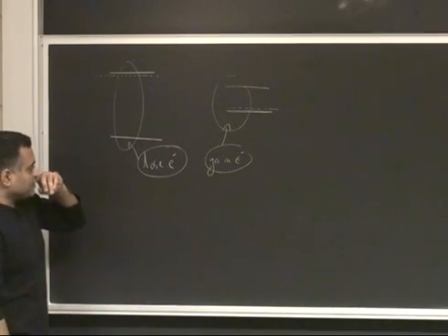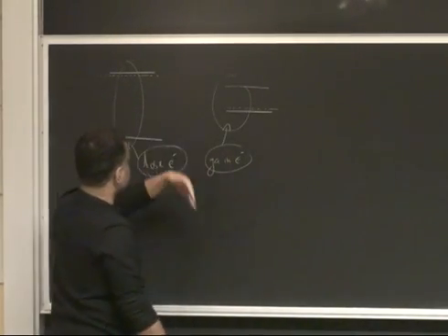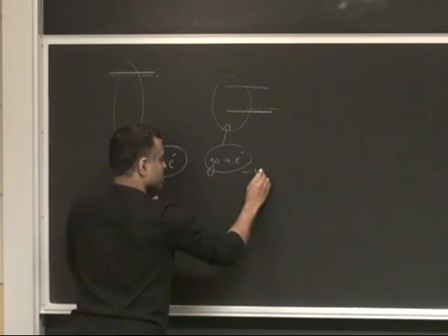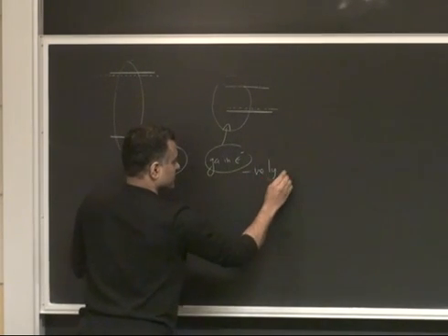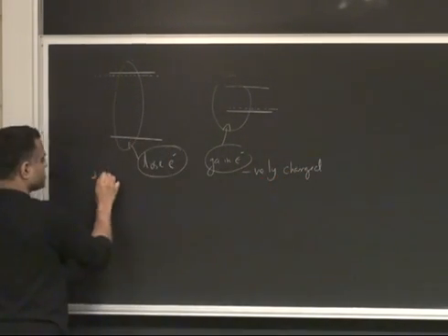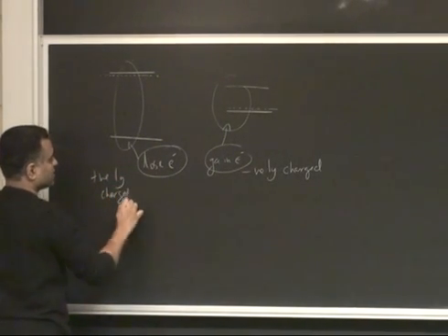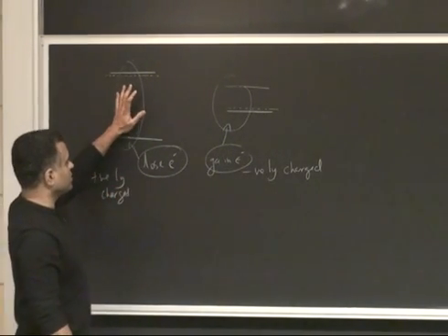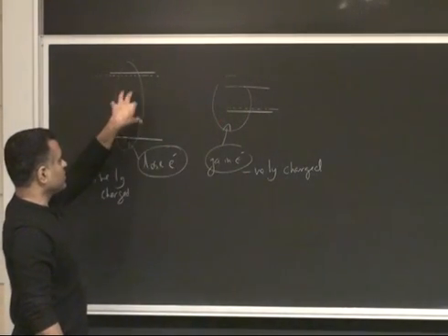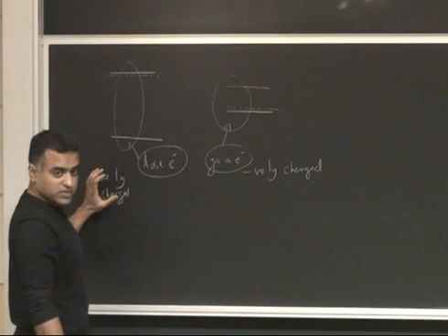And the way it works, the p-type layer ends up gaining electrons, meaning it gets negatively charged, and the n-type layer gets positively charged. But you see that this is really not different from a normal NP diode. If you had an N and a P, you remember you got a depletion region on the N side, you lose electrons, and you get positive charge.